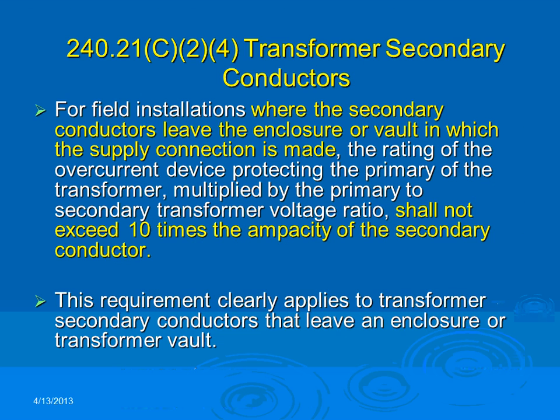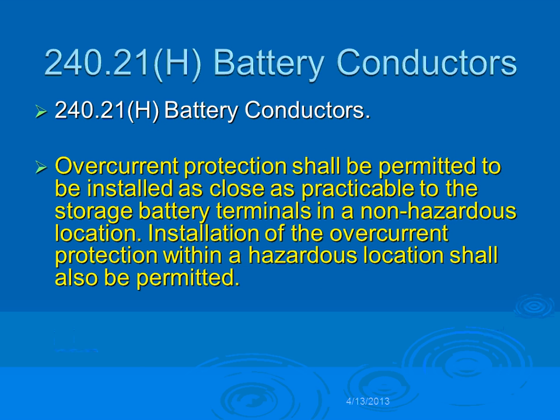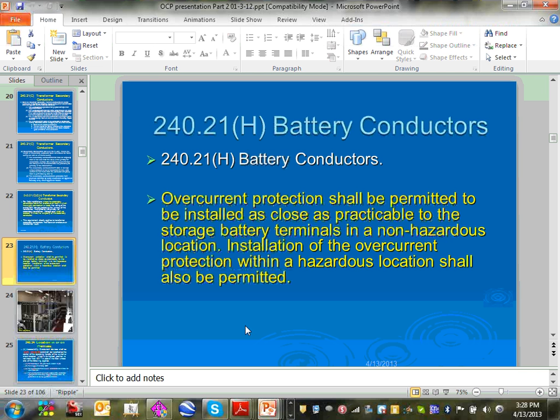Okay, talk about that one. The conductor shall not be 10. Okay, we talked about that. This is just a couple of things, guys, about the battery overcurrent protection device, as long as we're on it. It is permitted to be installed as close as practical to the storage batteries, but not in the hazardous location.